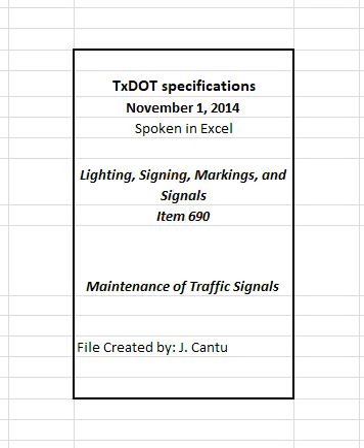4.14 Flashing beacon controller cabinet. Install, repair, replace, remove, or modify flasher cabinet. Plumb and tighten the cabinet. Coil all cabling that enters the cabinet neatly on the cabinet floor. Mark and terminate each cable as shown on the plans, or as directed.